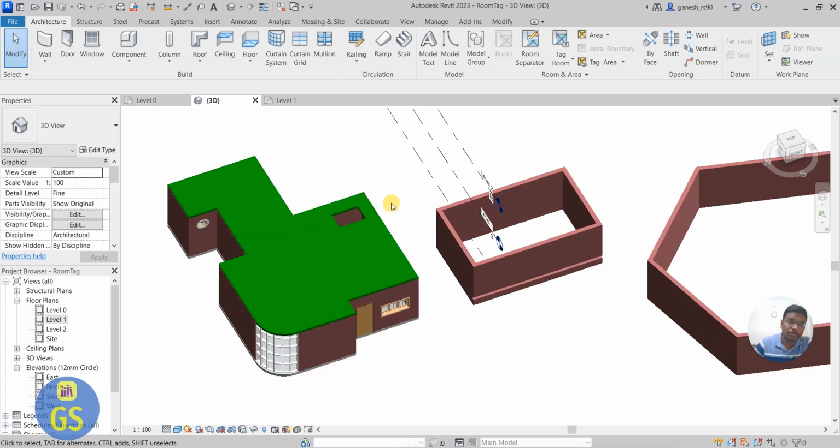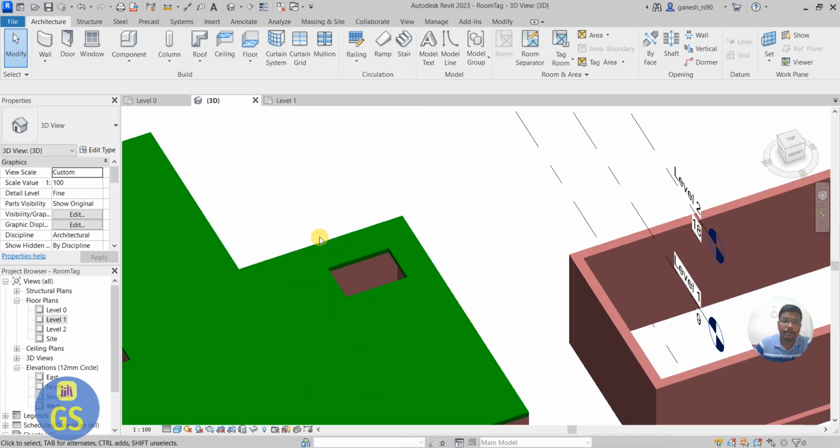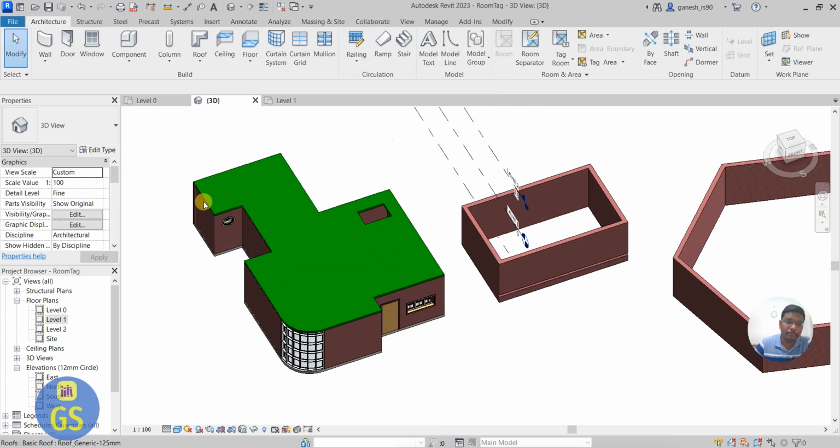Further that, what you want to know is let's go for your railings. So what is called a railing? So railing is basically a boundary protection or kind of handrails which you provide basically in staircase. So here is the railing. So click on the railing and select by path. So in order to know this, keep it in plan view, so that will be much better.